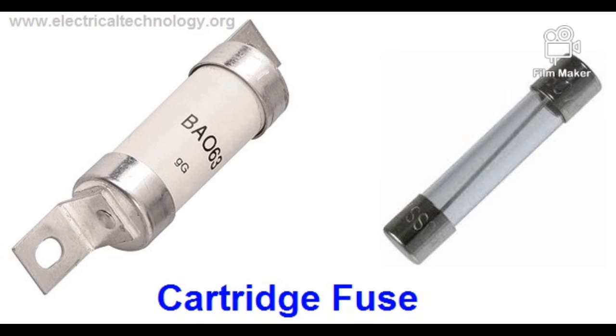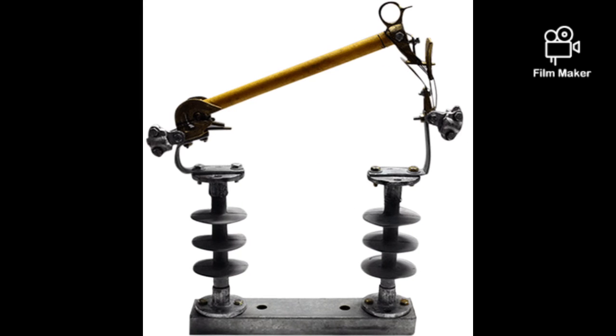Cartridge fuses are very similar to cartridge DC fuses. They consist of a transparent envelope surrounding the fuse elements. They can be plugged in, blade type, or screwed into a fixture, bolt type. Drop-out fuses. They contain a spring-loaded lever arm that retracts when a fault occurs and must be rewired and put back in place to resume normal operation. They are a type of expulsion fuse.